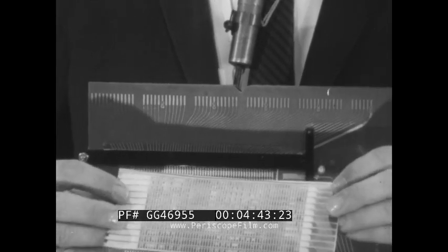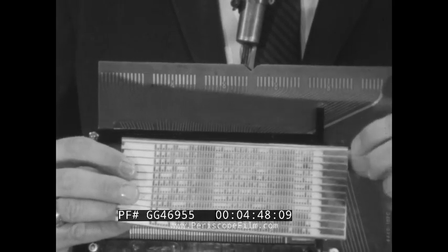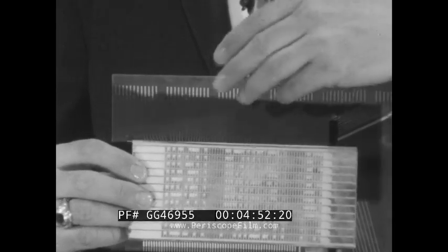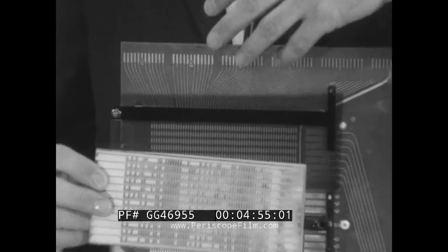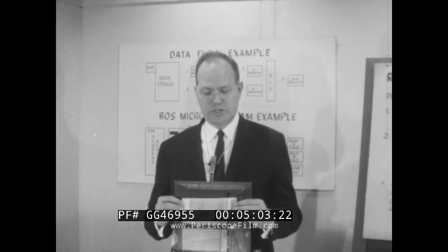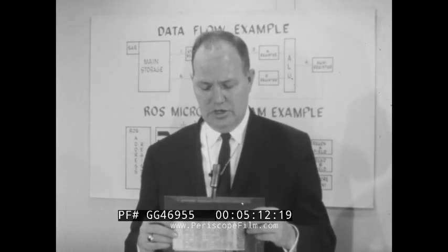In the case of the Model 30, the engineer determines a bit pattern for each micro-instruction word, and these bit patterns are sensed and sent out through this sense board into the machine such that they will cause various circuits to gate, open or close to allow the transition of data or the movement of data through the machine. Read-only storage also takes care of the problem of getting timed impulses through the proper circuits at the proper time, under control of the bit pattern.